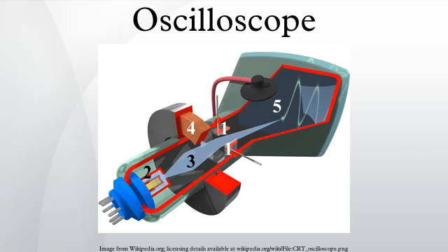Dual-beam oscilloscope. The dual-beam analog oscilloscope can display two signals simultaneously. A special dual-beam CRT generates and deflects two separate beams. Although multi-trace analog oscilloscopes can simulate a dual-beam display with chop and alternate sweeps, those features do not provide simultaneous displays. The disadvantages of the dual-trace oscilloscope are that it cannot switch quickly between the traces and it cannot capture two fast transient events. In order to avoid this problem, a dual-beam oscilloscope is used.